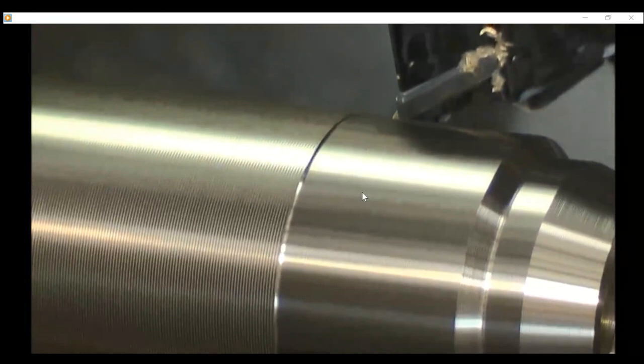Why do we have excellent quality here? Because here we're using a small depth of cut and small feed rate. We remove a small amount. Previously, we were removing a big amount of material. We had a very high feed rate, very high depth of cut. Depth of cut was big, feed rate was big, and the rotation speed was low. But now depth of cut is small. We're removing a small amount of material to get better quality, or the best quality.